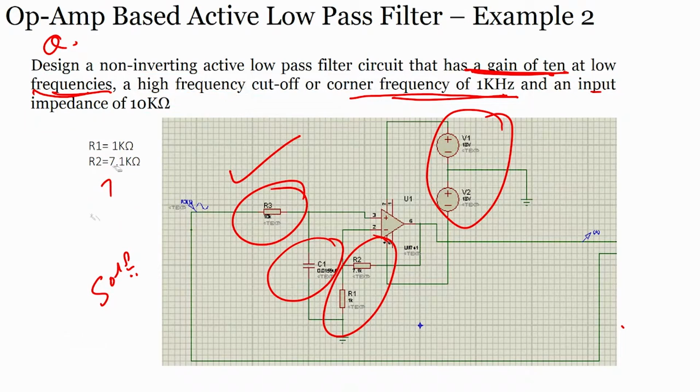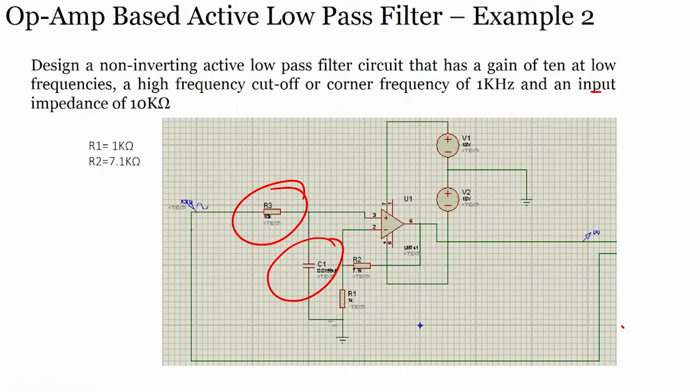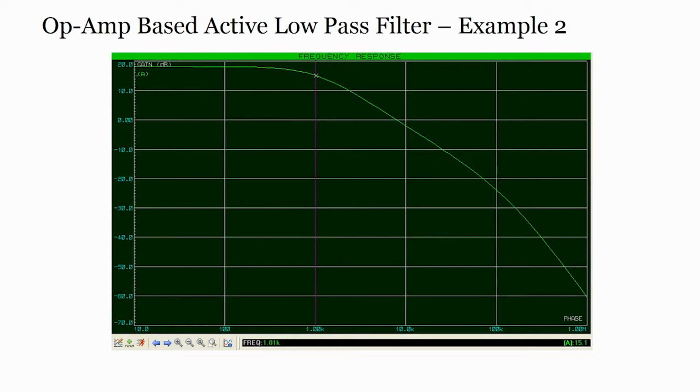So, let us come to the actual experiments and let us perform some experiments with low pass filter with passive and active components. When you actually perform this experiment and you see the signal, then you will find this particular slope, a fine slope here, and there will be some cutoff frequency somewhere next to here, and you can find this slope nearby the cutoff frequency. You can understand whether this is a single order or single pole active low pass filter. This is the amplitude and this is frequency.